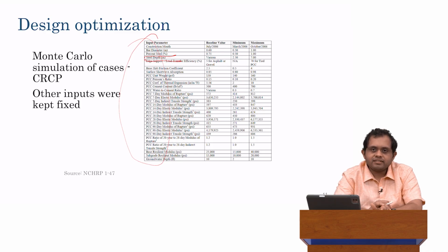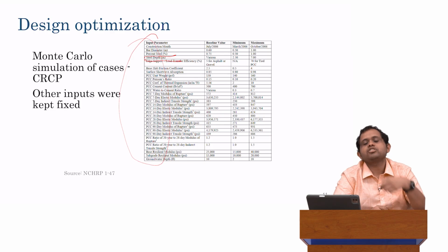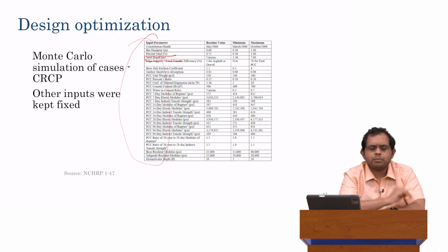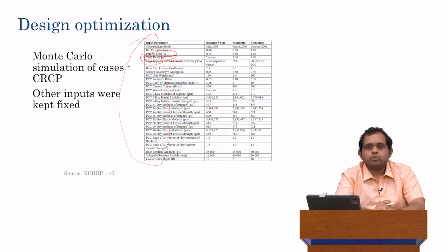But in CRCP, as we saw, the choice of steel depth has a strong impact on the crack width, and the crack width then has an impact on load transfer, which in turn affects the stresses developed, and so on, all the way out to punchouts. So please review that lecture on CRCP design. It was only a couple of lectures ago, if you've forgotten any of this. Most of the inputs are the same for CRCP, but the steel-related ones are a relatively new input.